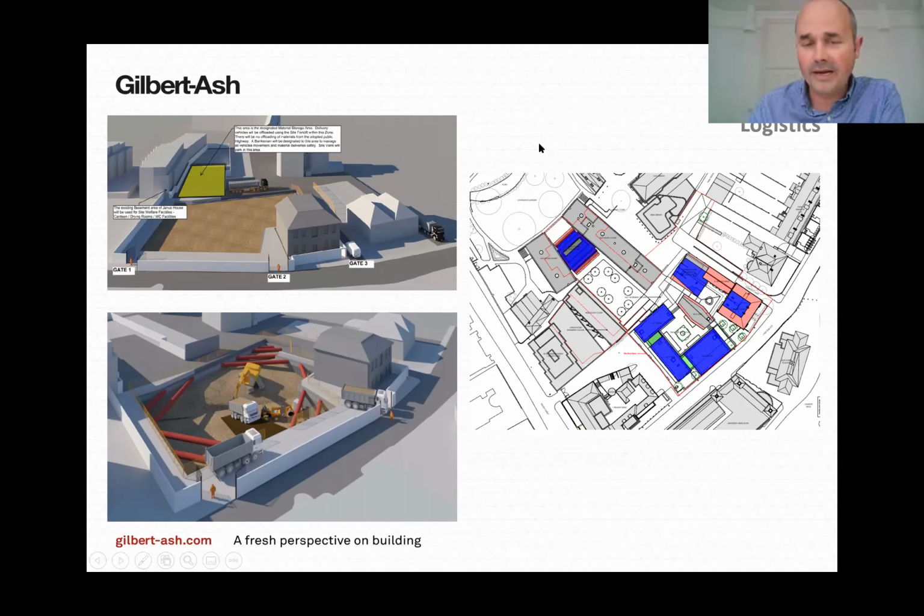One of the main things we had to concentrate on early on with the logistics was working through how we were going to manage the basement construction. As you can see in the bottom image, we applied to the local council to close the footpath adjacent to our site and run along Park Terrace, which allowed us to create more access to get the muck-away lorries into the site. In the next video, you'll see a part on the site access, which will demonstrate how the whole system, from conception at tender stage, working it through with the council, is now up and running and seems to be working quite well.